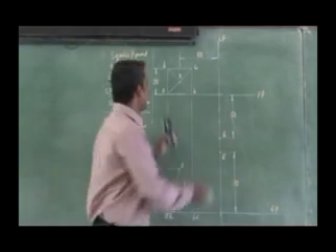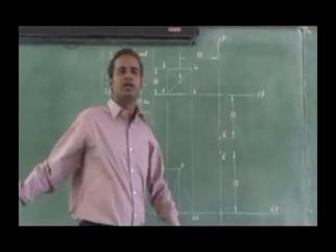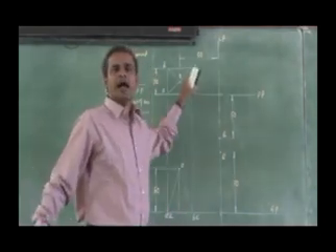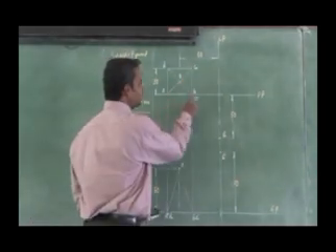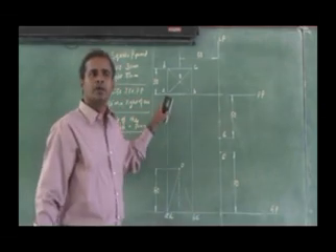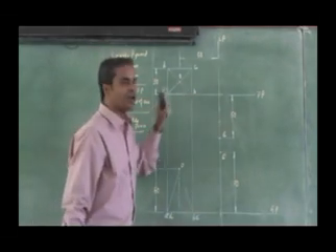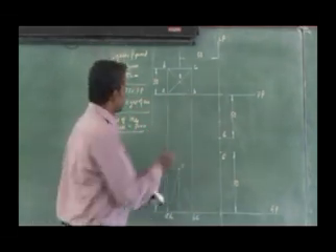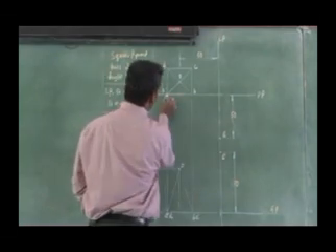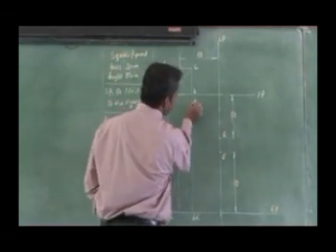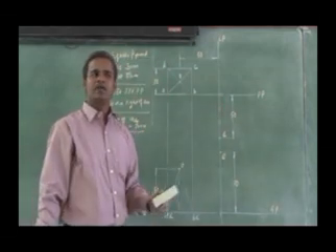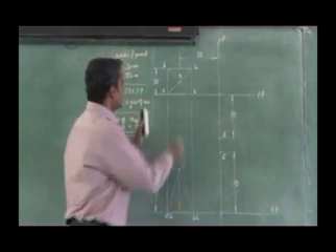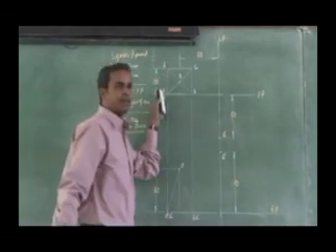Then you try to get the intercept of all the corners, including the apex. So you see here, what is the intercept of A and B? Tell me. If I join it to station point E with a visual ray line, wherever it intersects the picture plane, what is the intercept of A and B?